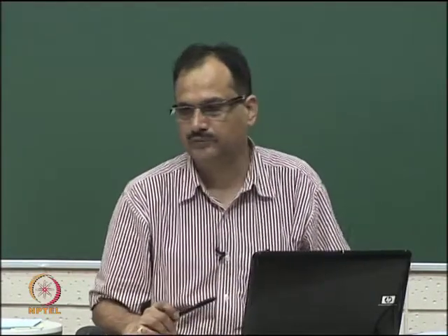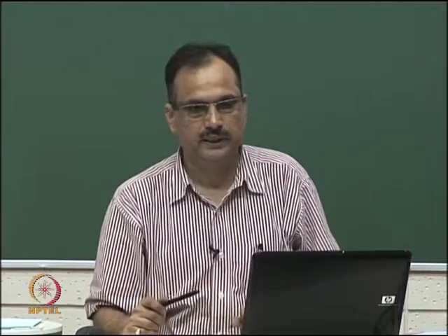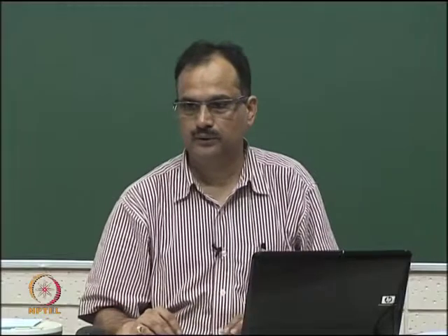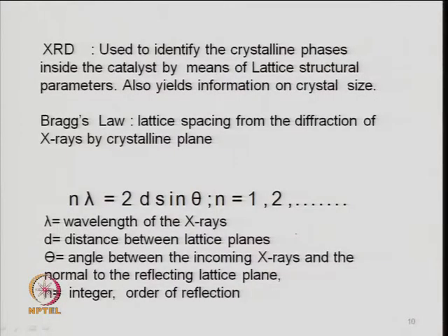So, there can be different kinds of X-ray sources, of different beam energy, and then you see at what angle there is a diffraction. It may be up to a certain depth, or from the surface, depending on the beam energy. This is what we are interested in here: the lattice structural parameter. And if you go further into detail, you can get the crystal size also, because that is related to the peak width.